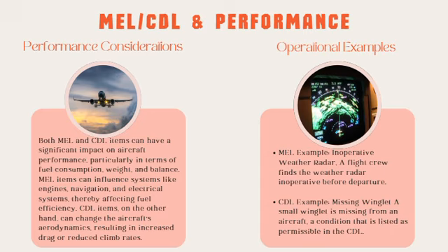When MEL items affect components such as anti-ice systems, hydraulic systems, or certain flight controls, it may restrict the aircraft's operational capabilities, potentially limiting operations in adverse weather or increasing fuel usage. CDL items such as missing fairings or control surface panels can increase drag, which impacts fuel consumption. This might require the crew to plan for additional fuel reserve or reduce the payload.